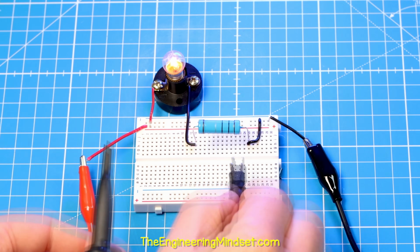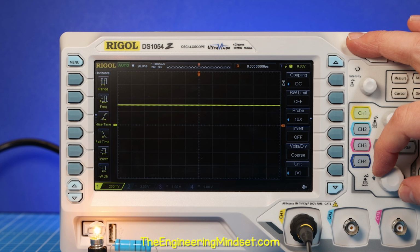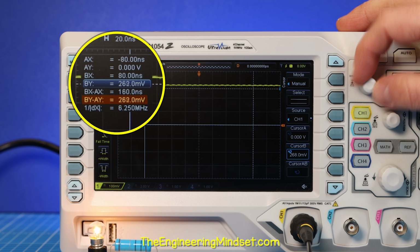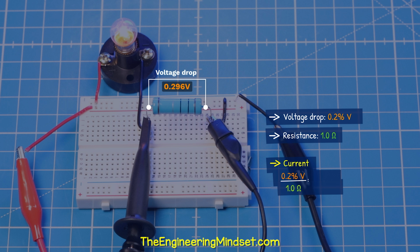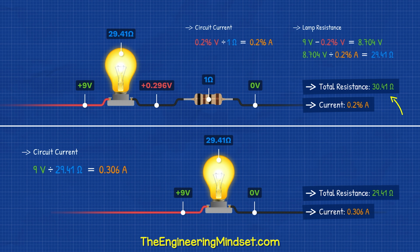Using channel 1, connect across the resistor to ground. I'll adjust the scale to see the signal. Then, using the horizontal cursors, we see the voltage drop. From that, we can find the current. The true value might be slightly different from our calculation, but do consider that with the shunt resistor removed, the total resistance of the circuit is slightly different, and this will change the applied voltage across the load. You might need to account for this.